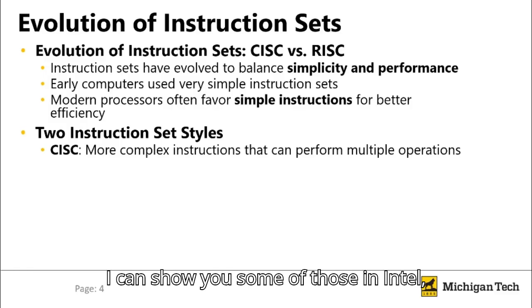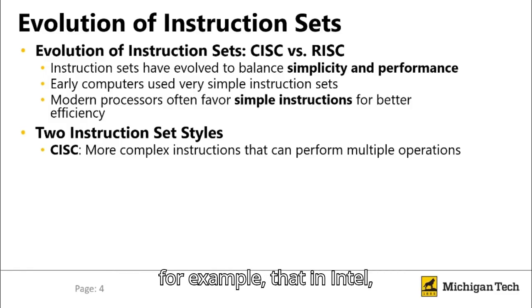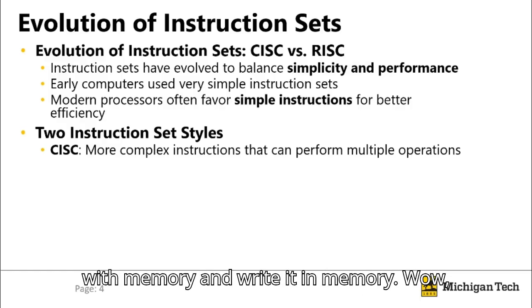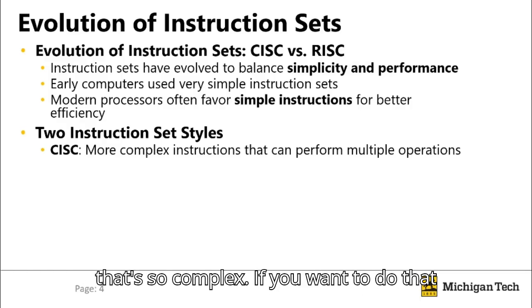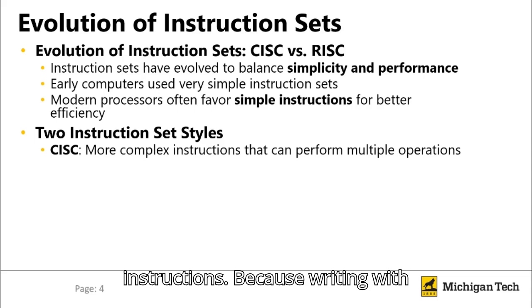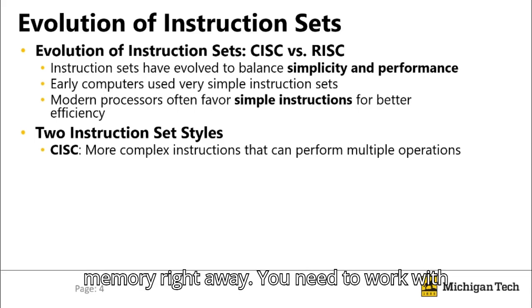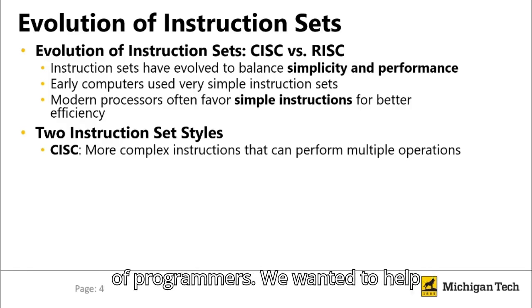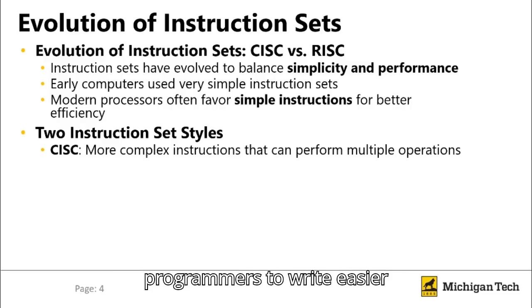I can show you some of those in Intel, for example, where you can add registers with memory and write the result to memory. Wow, that's so complex. If you want to do that with RISC-V, you need something like 10 instructions, because you are not allowed to write to memory right away. You need to work with registers because of performance and so forth. So yeah, that was because of programmers. We wanted to help programmers write more easily